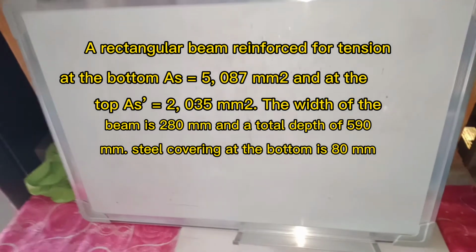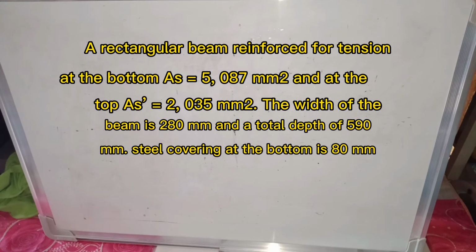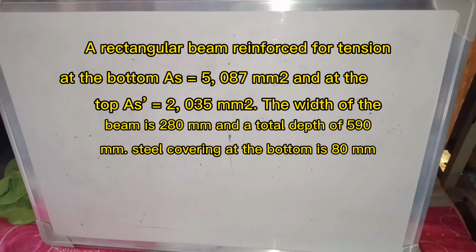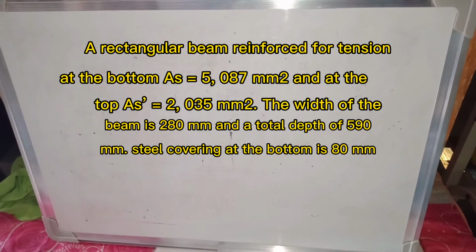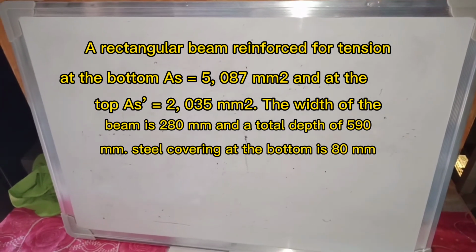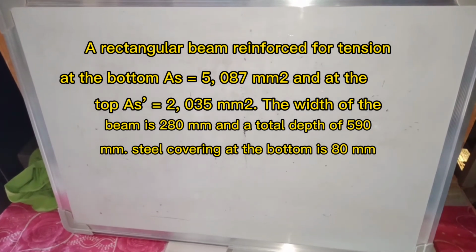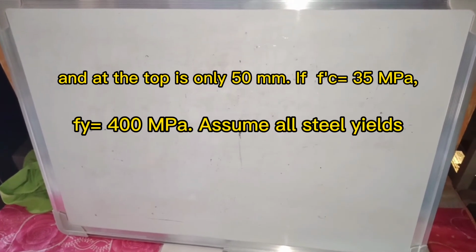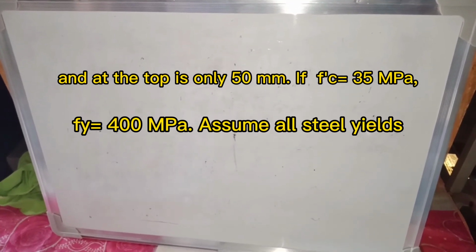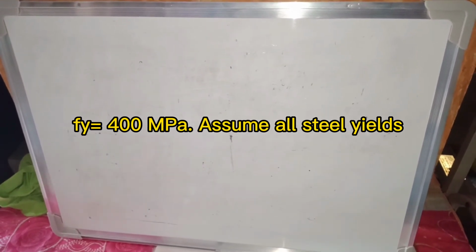So problem number 2 is a rectangular beam reinforced for tension at the bottom. Area of steel is equal to 5,087 mm squared, and at the top, area of steel is equal to 2,035 mm squared, with the width of the beam 280 mm and a total depth of 590 mm. Steel covering at the bottom is 80 mm and at the top is only 50 mm. If f'c is equal to 35 MPa, fy is equal to 400 MPa, assume all steel yields.